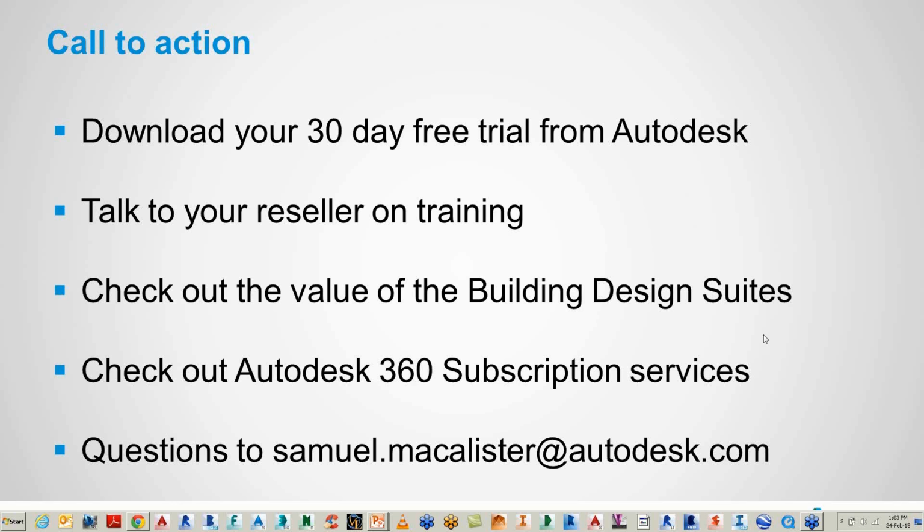you'd probably need to bring in your lighting plan and then populate it with your walls, your ceilings, and then host your Revit light fittings in there. And then if you need to do calculations, what we do have in the full version of Revit is a third-party add-in called Illum, and I'll just bring this up on my screen now.